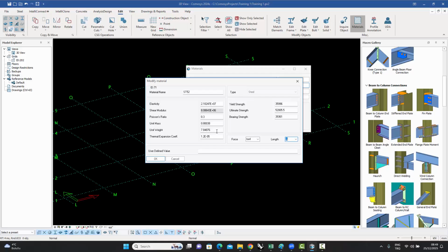But if there are some cuts on it, so you could have holes in the profile or some angular cuts, some things which force the program to then not be able to use the so many kilograms per meter value, in that case it reverts to this general per cubic meter value, because it does a volume analysis of how much volume you have in that particular piece. So it's going to use this particular number for creating your material takeoff tables.